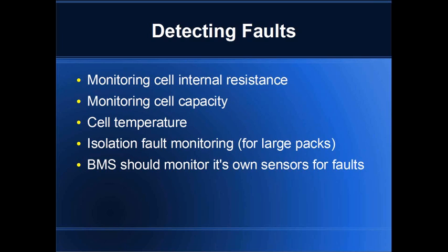That's usually conductive to some degree, and you can get some type of a reading, and that may be something that indicates an issue. Also, it's just good practice, in case you get condensation or metal debris or anything that's conductive. It's good to be able to monitor for those types of issues. We definitely see a number of design-related issues where shorts develop, and those are equally problematic as battery problems themselves.